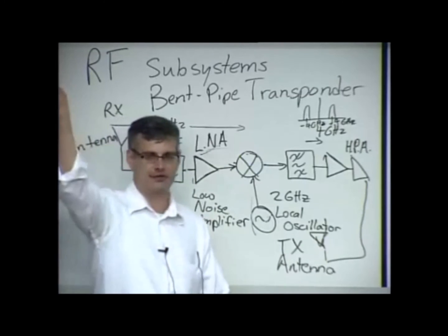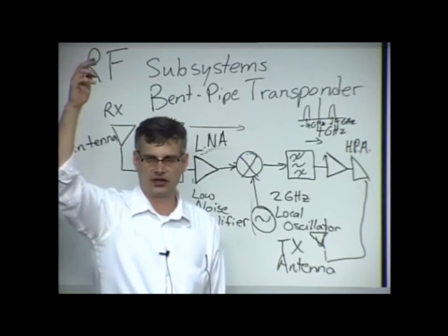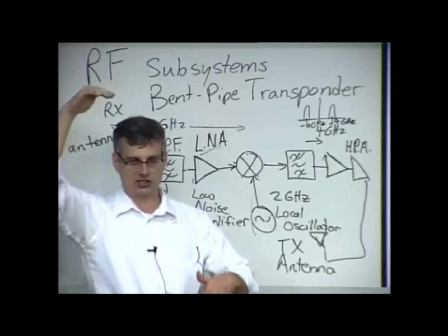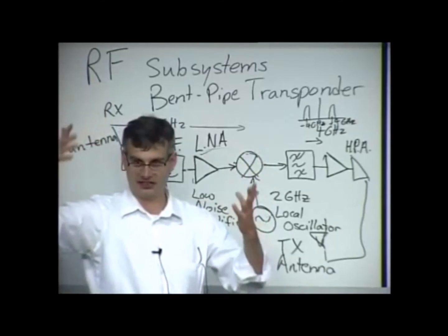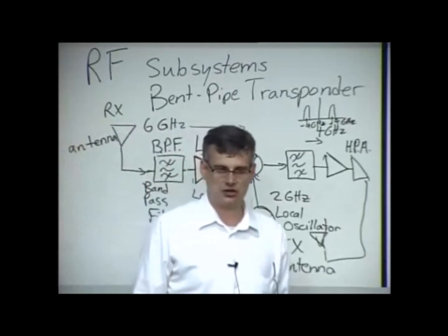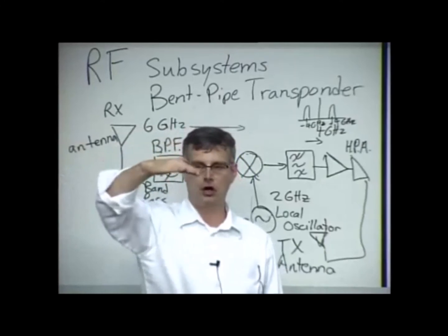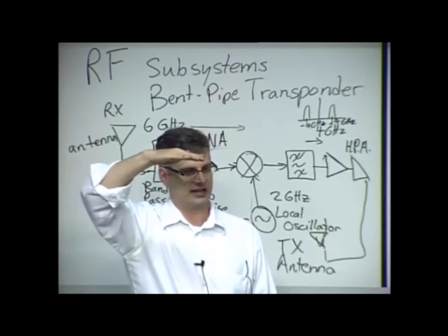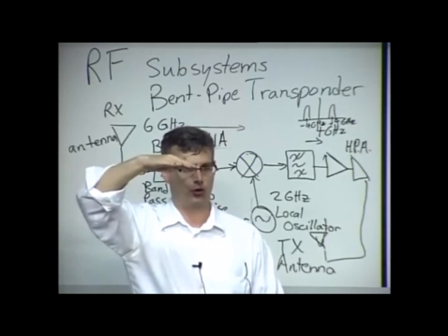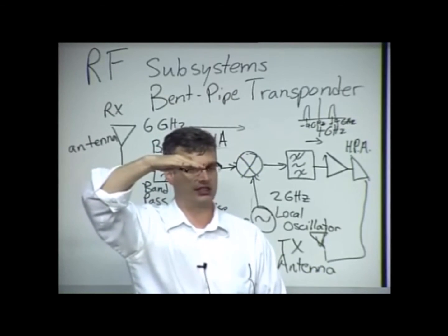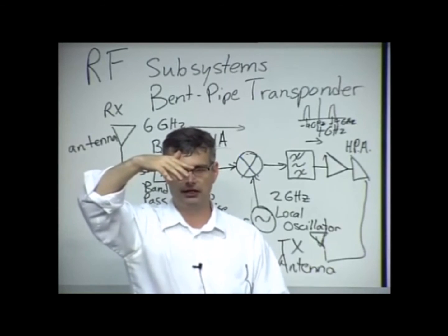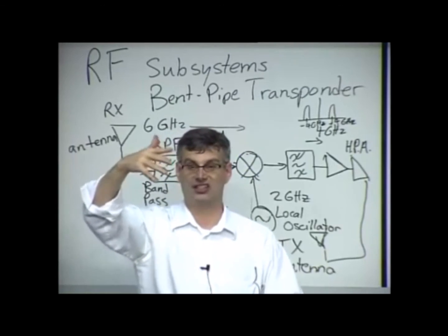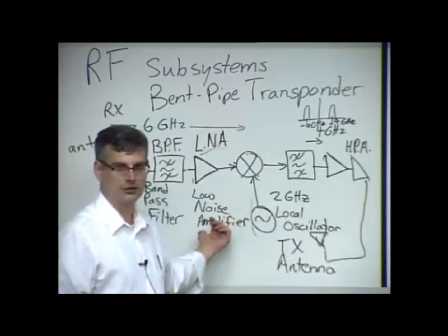Just because you've amplified the signal strength up to a certain degree, that noise is along for the ride and also got amplified, at least the noise that was in band. So that represents a plateau of performance that you'll never be able to overcome. Down at the Earth, you're going to add in more noise and interference to that signal that's already been corrupted. And so your signal-to-noise ratio on Earth is even worse than up here.